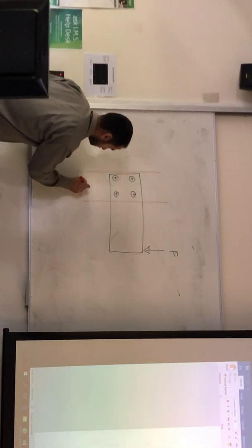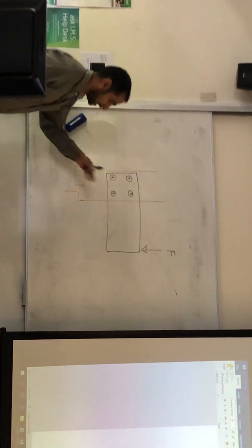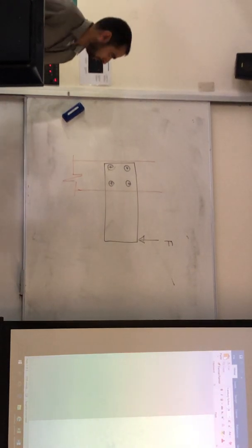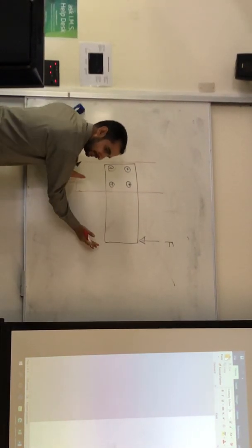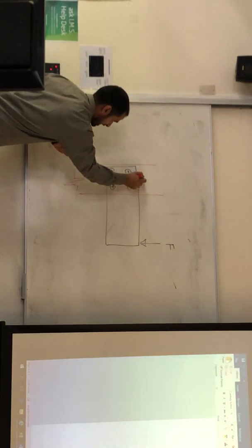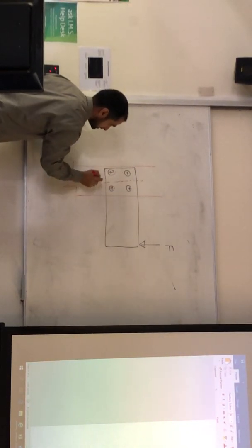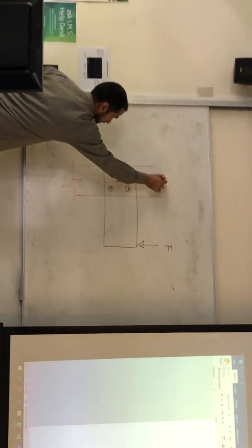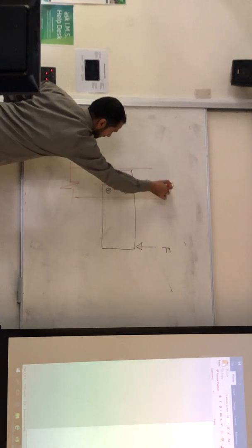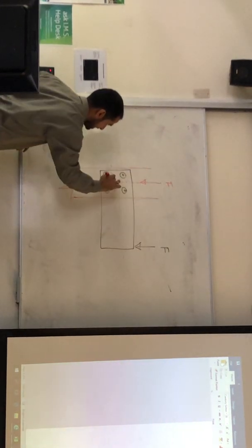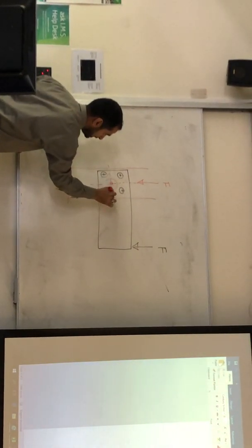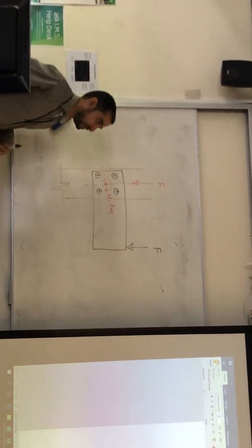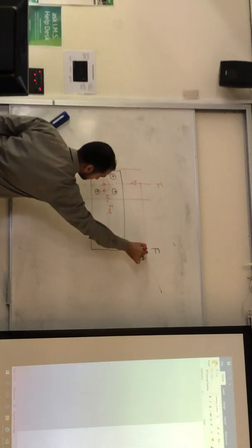So now, how do we deal with it? It's an eccentric load. So to transfer this load to the centroid here, that is the centroid of the bolt group, I have to replace that F with the F here and a moment, which is equal to F times e, where e is this distance here.